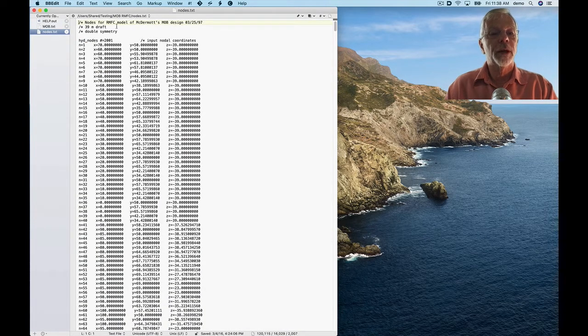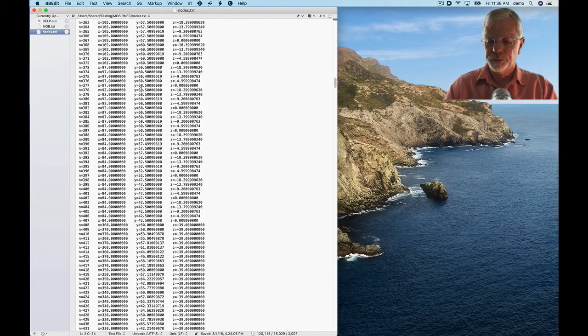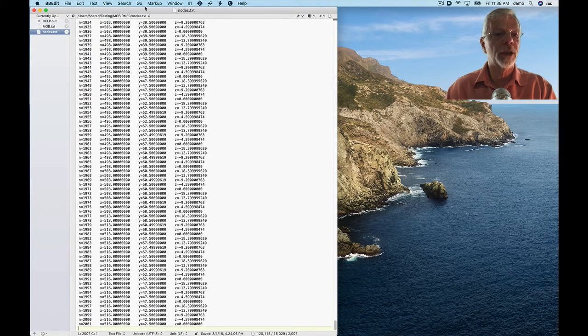It just gives some information. The slash star asterisk, of course, means it's a comment. So there are 2001 nodal coordinates. Remember, we're only modeling the upper quadrant, the part of the structure that is in the positive x, positive y coordinates, because we're using double symmetry. So that's 2000 nodes, and that's the end of that file.